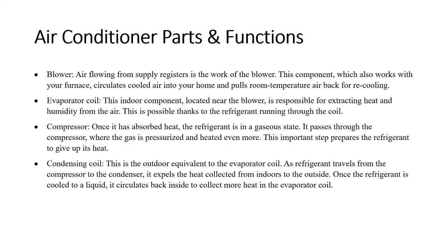My topic is air conditioner parts and functions. Blower. Air flowing from supply registers is the work of the blower. This component, which also works with your furnace, circulates cooled air into your home and pulls room temperature air back for recooling. Evaporator coil. This indoor component, located near the blower, is responsible for extracting heat and humidity from the air. This is possible thanks to the refrigerant running through the coil.